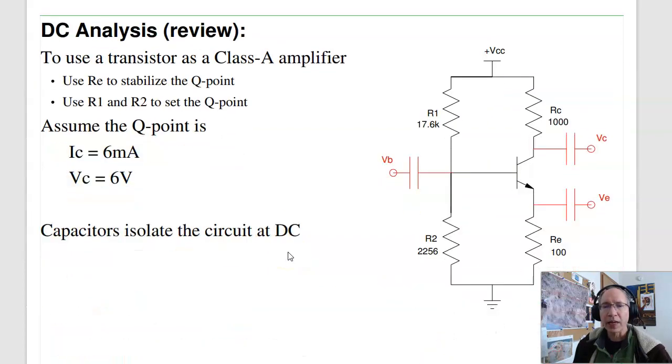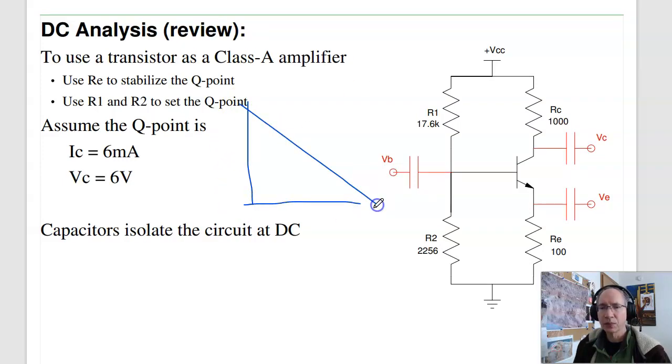Now, where we're at is, in the previous lectures we looked at taking a transistor circuit like this, finding the resistors to bias you in the active region. So again, if you draw the load line for VCE versus IC, it's going to look like this. I chose RE. Well, RE is not 0. That allows me to stabilize the Q point. I chose R1 and R2 so that the Q point is stabilized for variations in beta, and chose them so that the Q point was at 6 volts, right in the middle, and this is 12 volts.